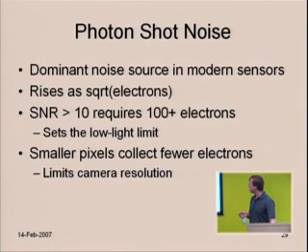This gets back to a question asked earlier. As we get newer sensors, the sensors have smaller pixels because that makes them cheaper to produce, but smaller pixels behind the same lens capture less light. You have fewer electrons, a smaller signal-to-noise ratio, and so the overall image looks worse. This is essentially the limit on camera resolution, and it's an interesting limit because we're almost up against physics.